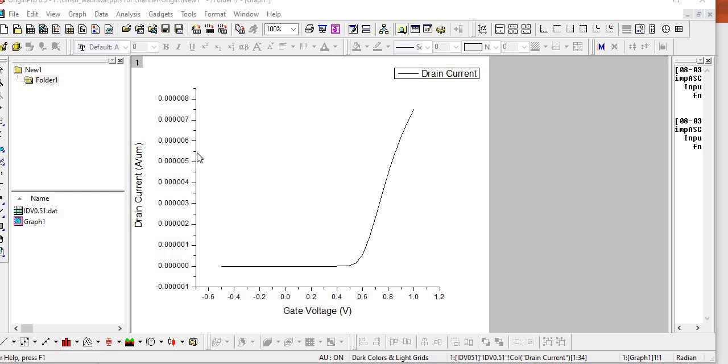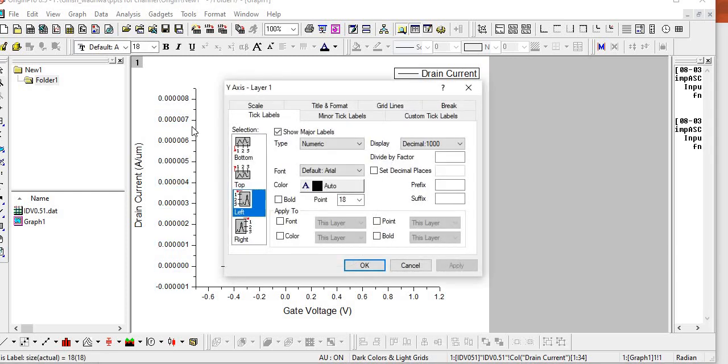So this side is basically linear. This is the linear graph, a linear current graph. I want to change it to log. So what will I do? I will double click on this. Now you will see this kind of pop-up. You can see that there are different kinds of options that you can choose to make this graph very presentable. You can also select the different axes on the same graph. You don't have to worry about clicking on each side.